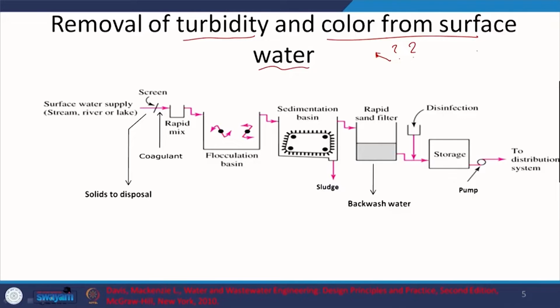And the other one uses a wastewater treatment process based system to be able to treat this surface water. Why is that? Because River Yamuna, depending on when you sample, you are going to have high BOD, and maybe COD to be 70, 80 milligram per liter, right? And here the issue is, if you look at the dissolved organic carbon, it will be around 8 to 9 to 12 milligram per liter.